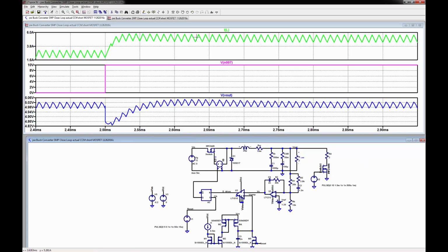We're going to begin at the 5 amps, and then we're going to jump down to the 2.5. Well, guess what? When we jump down and release this to 2.5, where's the other 2.5? You can't put 5 amps here. So what's going to happen is the rest, one 2.5 amps is going to go to here, and the other is going to be dumped into this cap. Hence, plus minus, it increases it. That's why you get a voltage up. And you're going to see that on the other end when we look at that.